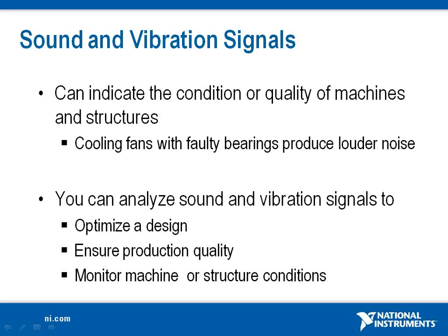For example, when a cooling fan spins, it generates noise. High-quality cooling fans produce lower levels of noise. Defective cooling fans, for example ones with a bearing defect or broken blade, produce higher levels of noise.